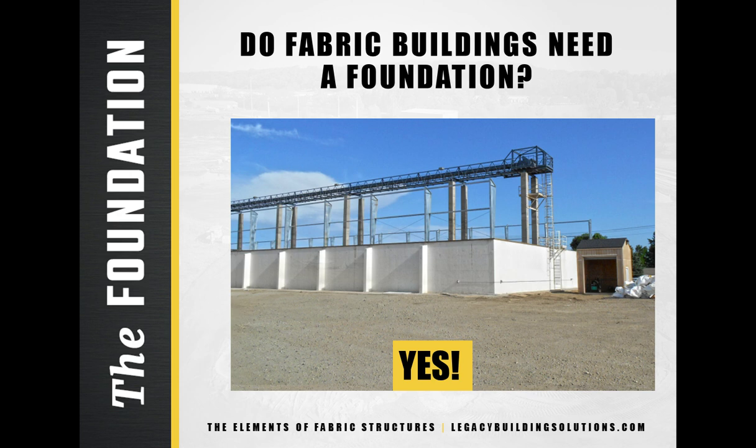Fabric structures, just like any pre-engineered metal building, are lightweight structures. The most critical functions of the foundation are to ensure the structure remains securely attached to the ground during wind events and that the base of the foundation does not push out when snow and wind loads are applied. While it may be tempting to settle for a temporary foundation to keep the building costs low, that compromise may lead to devastating consequences in the future as the building and soil shift and move.